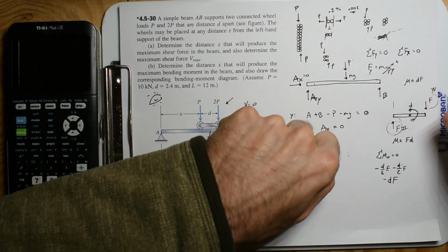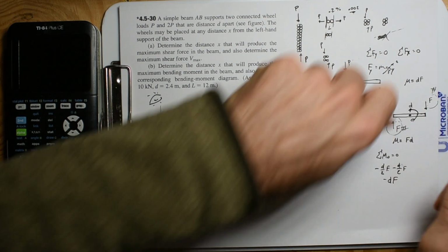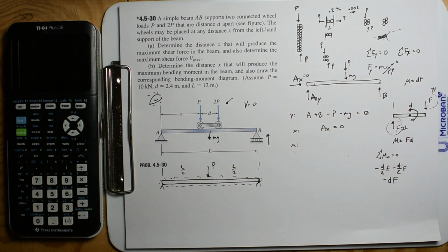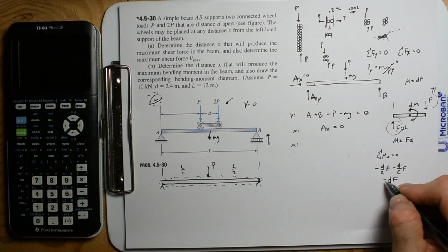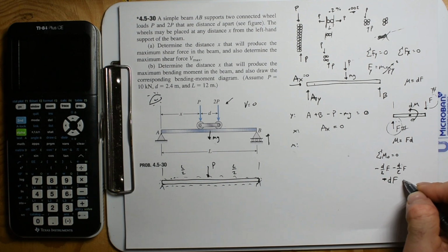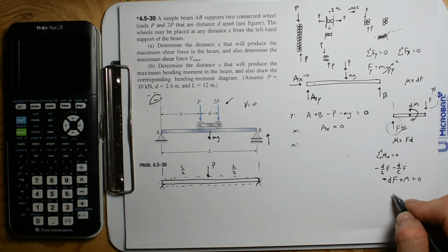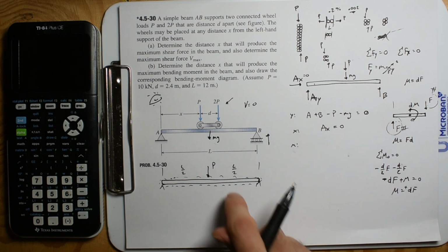And then start to, well, let's see. So if this is going this way, yeah, we could attach something at the center of this and torque it the opposite way. And this moment right here would have to equal dF, because we'd have negative dF plus that moment has to equal 0. That's the equation, and we have that moment is dF. So it's positive dF. Cool, so that's what we're going to do right here.